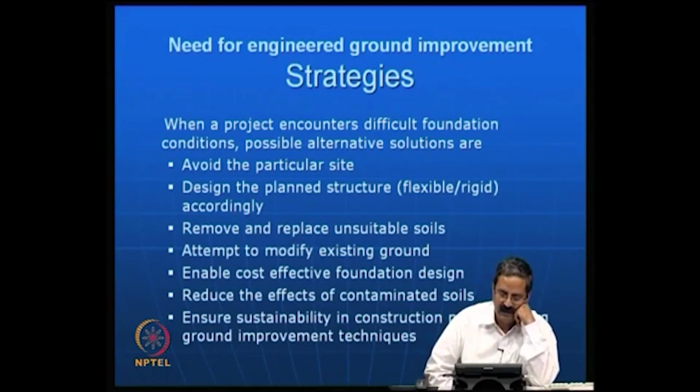Of course, there are many other alternatives people have been looking at. The other one is to remove and replace with suitable soils. In fact, if the expansive soil is only a 1 meter thick deposit, replace it. Even our road thickness is about 1 meter or 0.8 meters. So, just go ahead and replace the whole expansive soil area and put in the regular material you want. Removal and replacement is sometimes okay, but it is not easy all the time, because you have the same soil next to it, and it may create additional problems.